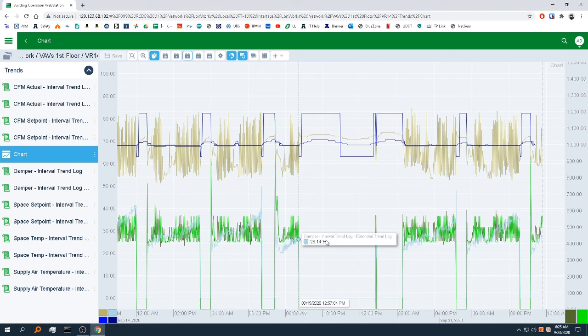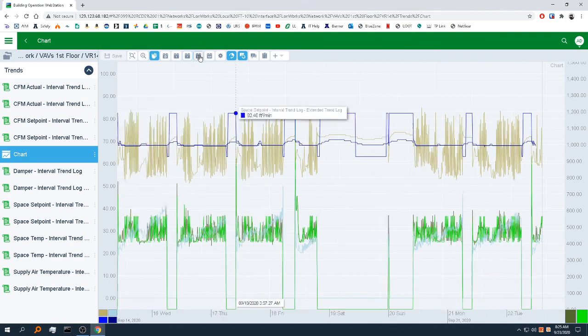For energy efficiency stuff that Zach often has us look at, this is a really good indicator to make sure that the unit is shutting off at night and not remaining on all night. And right here you can see the pattern. Today is Wednesday. You can tell that this section right here is Tuesday, this is Monday, this is the weekend, and it was off. Looks like it bumped on for just a minute here, and then you can tell there's a modified schedule probably on Saturday, and then here's Friday, Thursday, so on and so forth.